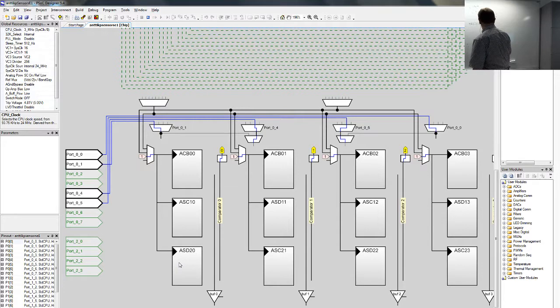So basically the Q factors and also the cutoff frequencies depend on the values here. Well, the capacitors you can actually tune by selecting from a set of capacitors. You can always select a certain range. That can be done by just having a multiplexer for capacitors.